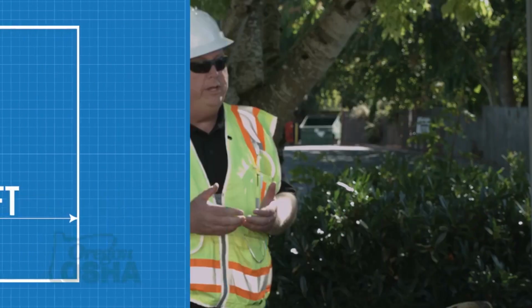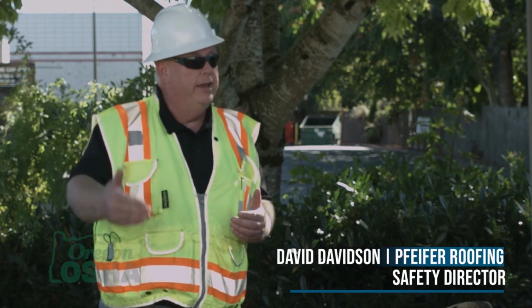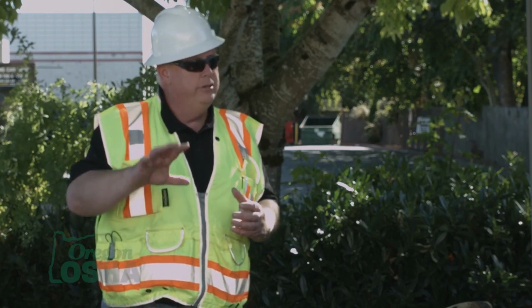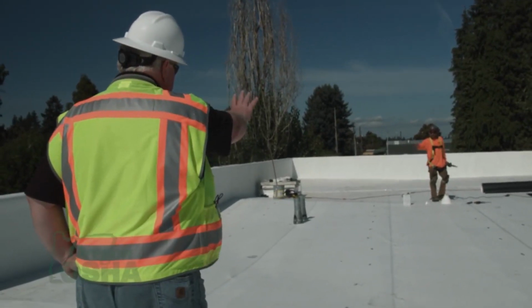When we employ the safety monitor system, it's for some of the work that we have to do outside of the safety line. So a couple of things that you can do there. You can be tied off. Sometimes that's very difficult because of the anchor systems that you have to have. And again, we're doing membrane roof. So having the safety monitor to keep an eye on those workers outside of the safety line is a way that we can do it safely, making sure that everyone stays safe. So it's just another fall protection measure that we can use in those situations.